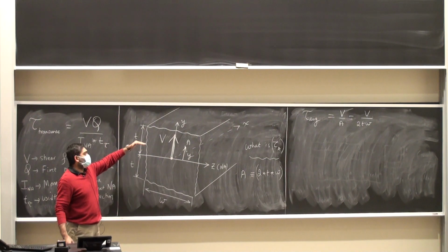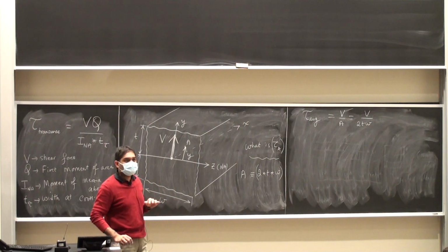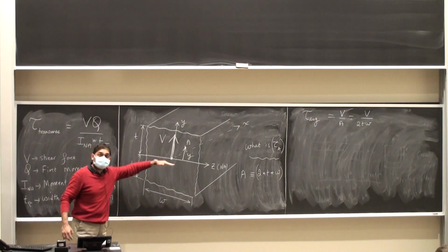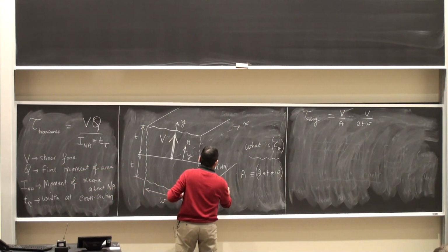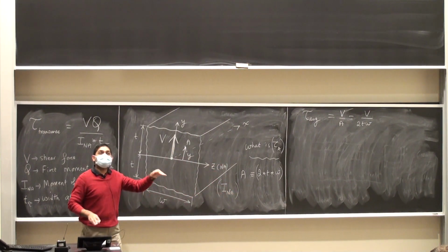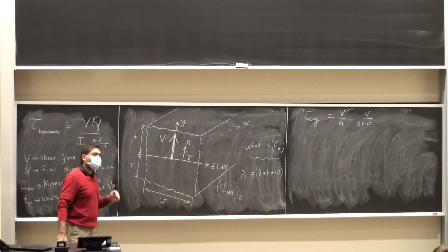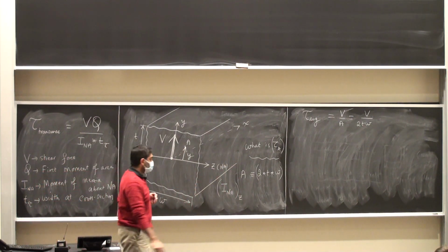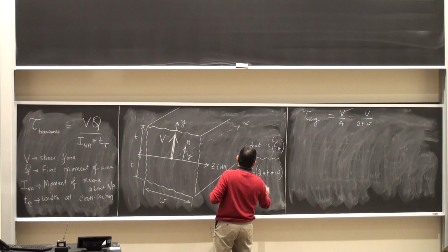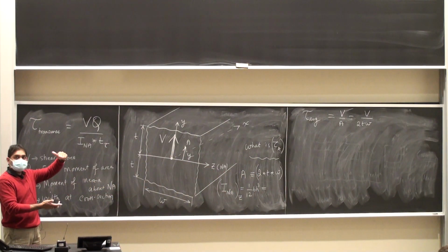The moment of inertia about the neutral axis for a rectangular cross section is something that I want you to remember. So for the neutral axis being the direction it is pointing here, moment of inertia I N A, if the neutral axis is Z, then this is going to be 1 by 12 times the base times the height cube, where my base is W for the rectangle and the height is 2T.